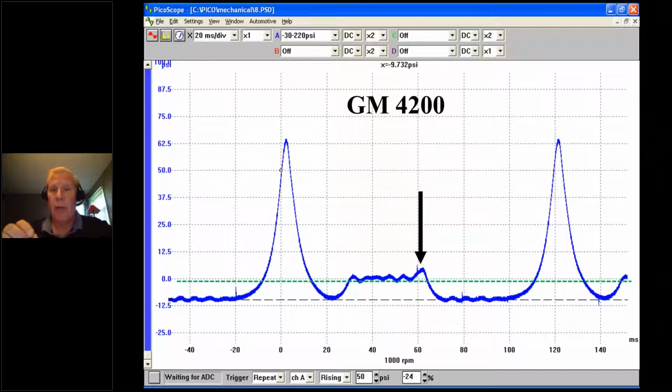If you think about it logically, and I realize with my webcam you probably can't see my hands as well as I would like, imagine my piston is moving up on that exhaust stroke and it's approaching top dead center. Normally the exhaust valve would still be open and there's no back pressure in the cylinder. But if that valve closes too soon, there will be some trapped pressure and we'll see a positive going pressure pulse. So the bottom line on that 4200, that's perfectly normal. Now, if that engine did not have cam phasing, I probably wouldn't say that. It brings me back to this 1.4.